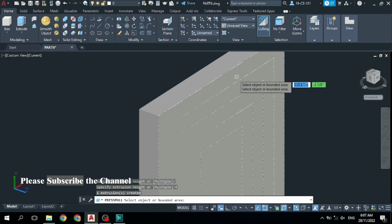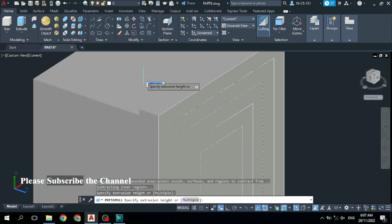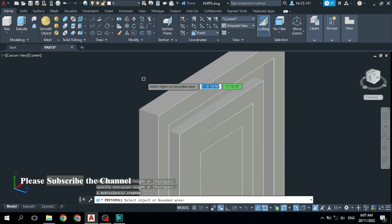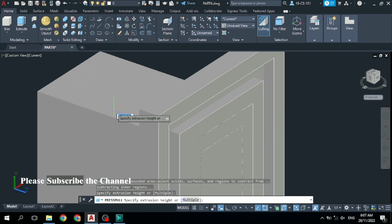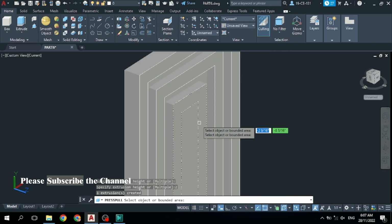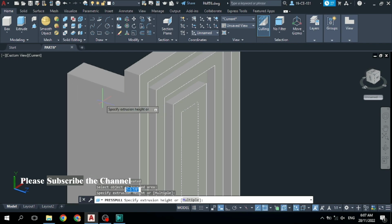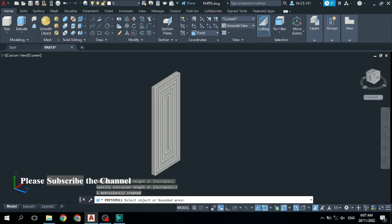And then after that, leave this rectangle and come to the second one and select it and go to the back side, type 2 inches and press enter. Then again leave this one and come to this third one and select it and go to this side 2 inches and press enter. And after that, come to this last one, select it and go to this side, type 2 inches distance and press enter. Now you can see this door is done and press enter to finish the command.